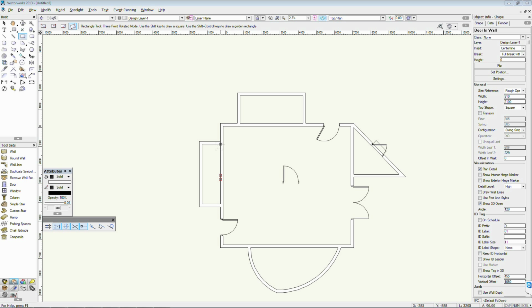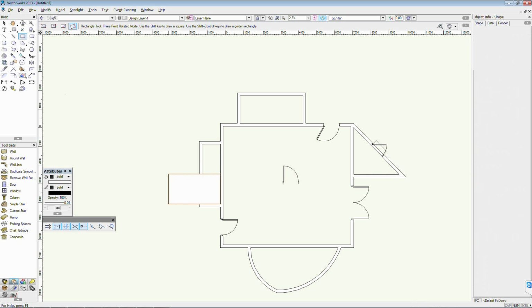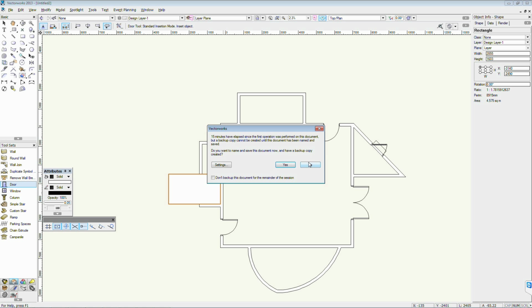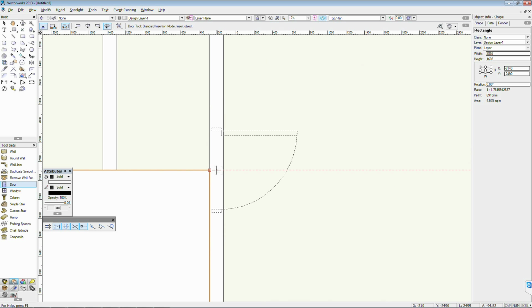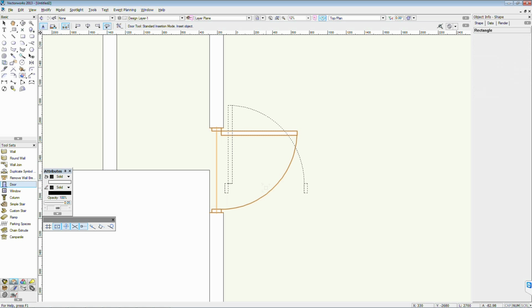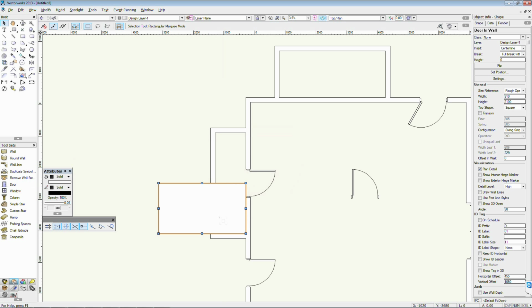3205. I can just type divide by 2 in there. So I'll normally mark out whenever I'm doing a plan like this, and then I'll find my door, make that my marker point, make sure I zoom in and lock it in. You can see how I've approached that corner, it's snapped, and I'm inside the wall. Left click, choose a direction. Let's say this one opens outwards, probably a cupboard, and there we go. And it takes a moment for me to load my object info over there.